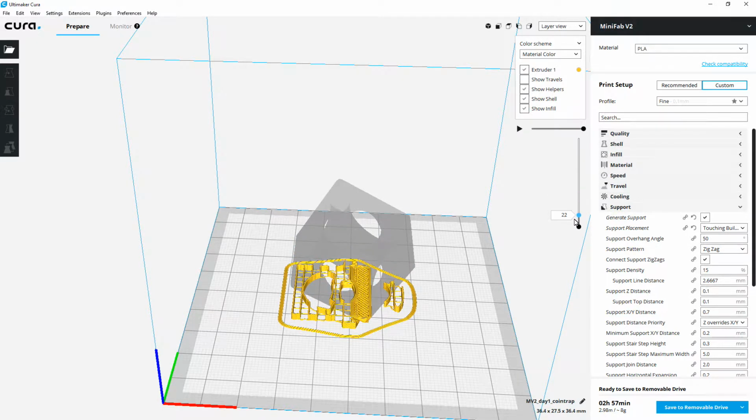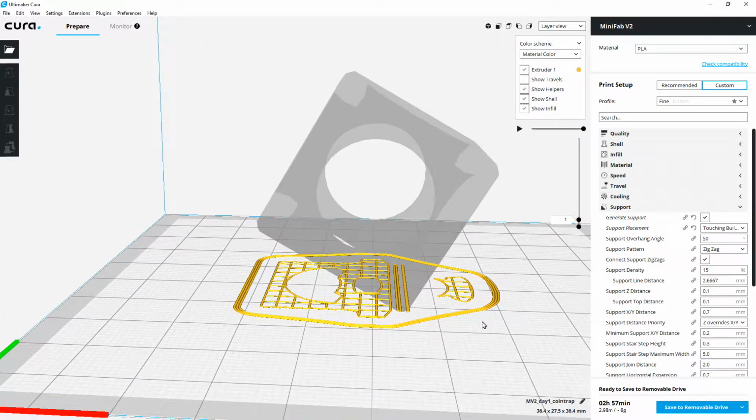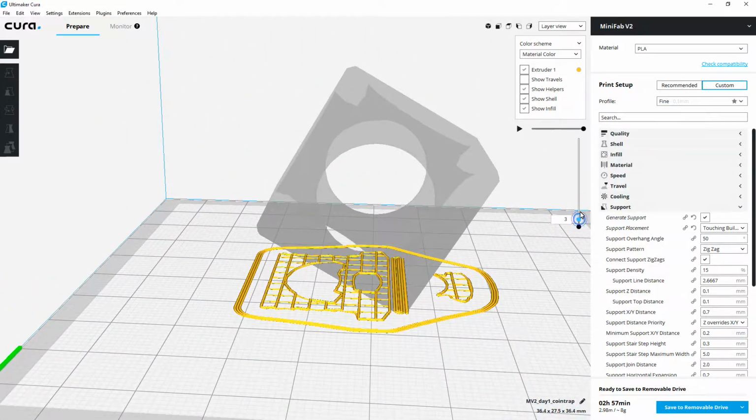Now this has some really cool things. You can print things that have a lot of curves, and it also helps to increase how much footprint the object has. So here's the first layer, and you can see that all of a sudden there's a lot more footprint now. So you actually probably could print the cube on its edge like this. It'd be interesting to try. And it would only waste about 16 cents worth of plastic. So most filament is about 2 cents per gram, and we see that this is about 8 grams, so 16 cents worth of plastic to print this object. And we can see how it prints.